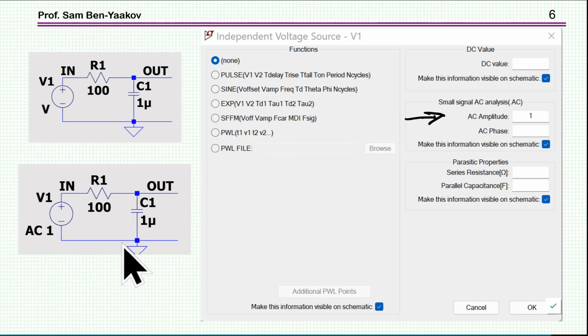Really doesn't matter. Nothing will burn here. Nothing will get warm or explode. It is just a mathematical calculation. What will happen is that the current will be 1,000 times larger. And what is important, the ratio between output and input will be the same. So a linear circuit is insensitive to the amplitude. Very, very important to remember that, because this is a source of confusion later on.